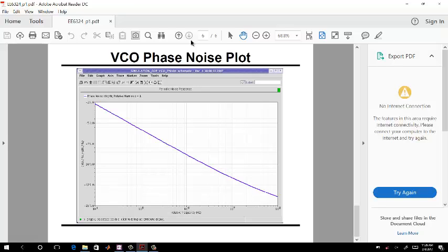So you can have an oscillator which gives you a certain phase noise. Now this phase noise you can use in your analysis to find how much jitter it will be. Means without closing the loop in circuit, you can find what is the actual noise of an oscillator. You can use that number in your analytical work, or just a simulation on equations. No closed loop simulation in schematic yet.